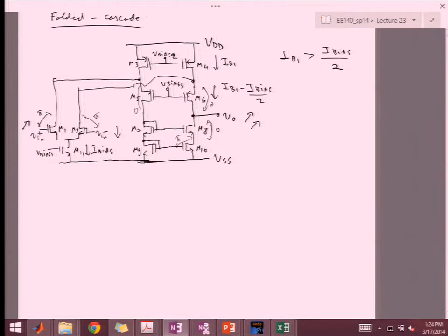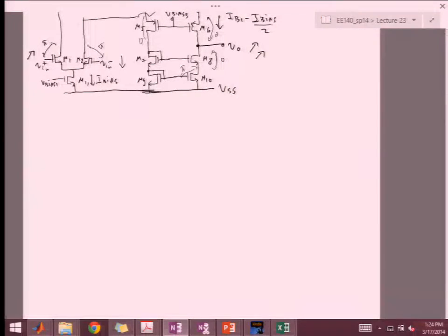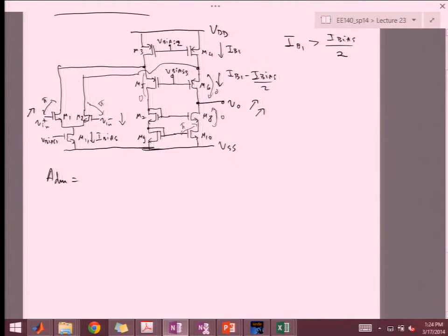Okay, let's take a look at what the gain is. We said that for the amplifier, multi-stage one, whatever, we always get this relationship, right? This just comes from the fact that I model any amplifier as GM V in, and this is V out, right? So my VO is minus GM R out V in. Right. Okay.